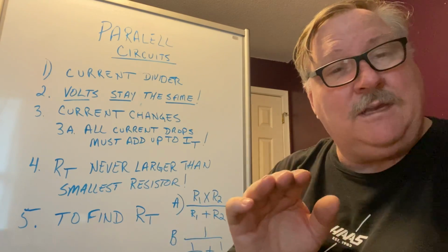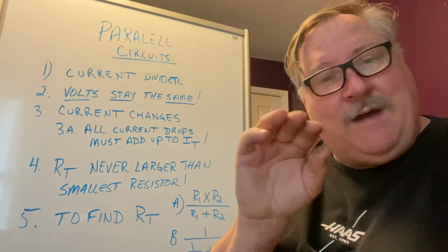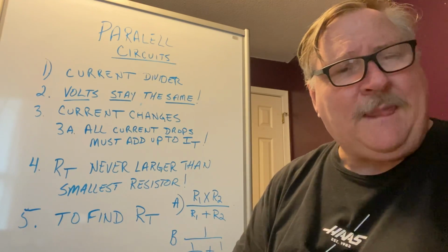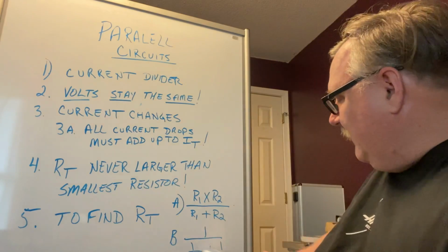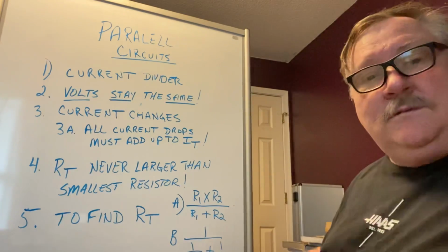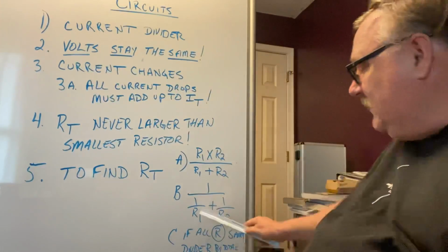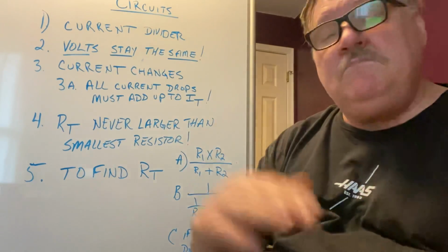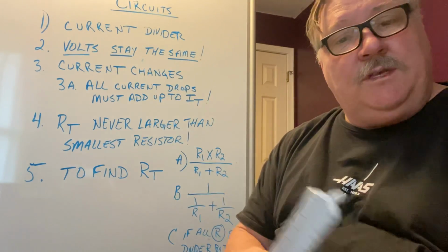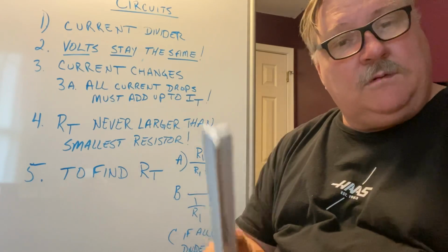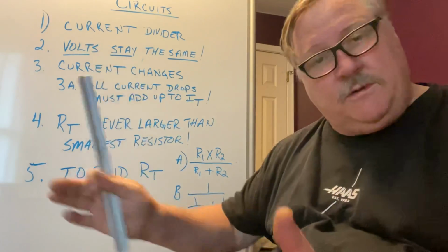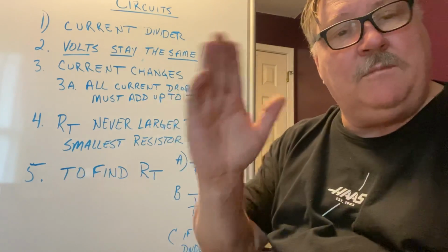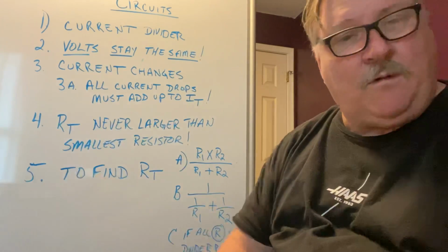Now, once we get those together, then we're going to take 1 and divide that by the sum of those two that have been added together. My example is just for 2. We could have 3, we could have 50. No limit to it. You still do your reciprocal of R1 plus reciprocal of R2, and so on and so forth. You get all those numbers, and you've got to do that last reciprocal: take the number 1 and divide it by the total sum of all of those.